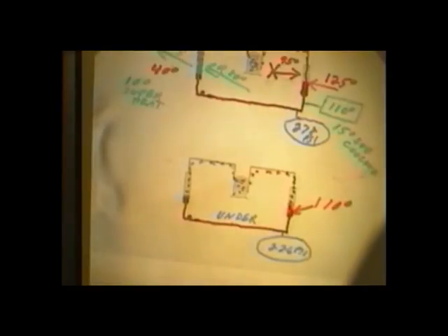How did you get that? Lower pressure, lower temperature. I'm only giving you this as an example; there's all kinds of ways to give you an example. What I did was, I said I want to bring my pressure down. So I came down to 200 and, where is it at? Right here, 226 psi. That gives me a saturation temperature of 110 degrees. Remember, if I know my pressure, I know what my saturation temperature is.